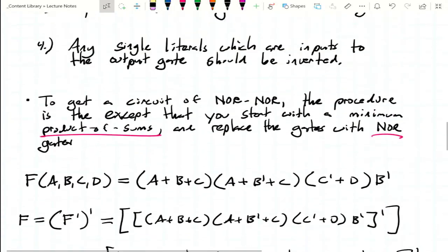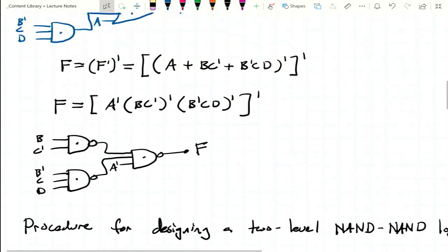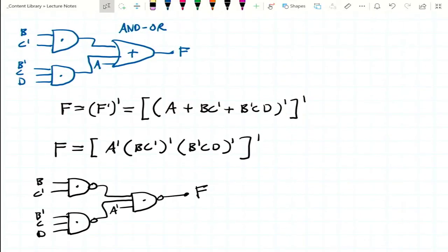our circuits that we just did. Even our two-level circuits still follow that same procedure, right? This two-level circuit is still a circuit that has an OR gate on the output. We converted all the gates to NAND gates, and this is level 1, which is an odd numbered level. That input single literal got inverted, right? But this is level 2, which is an even numbered level, so these input literals stay the same.